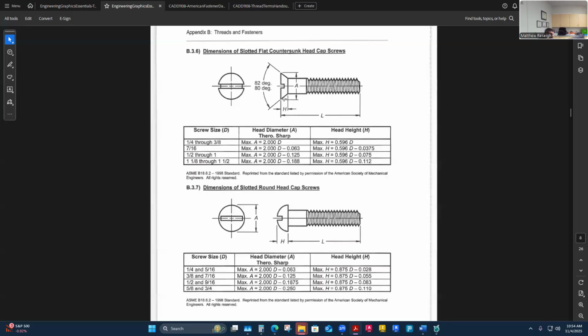It needs to seat nicely right up against the material it's holding against. Otherwise, the design intent is not there. So the degree that I machine my part to has to match my fastener. There are a few different degree increments used for these fasteners, so I have to be careful to order the right parts to match the right setup, because this surface needs to contact its mating surface completely.